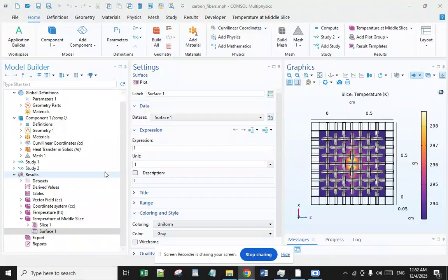The transfer direction x_t here in this picture measures the through-thickness transverse conductivity k_t, and the longitudinal direction x_l for this simulation. And rho is the fabric density calculated from the areal density of the fabric, rho_A, divided by the fabric thickness as measured during the experiment with a micrometer and the IR camera photographs.